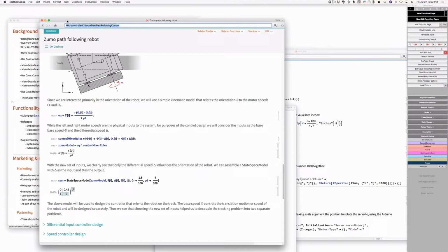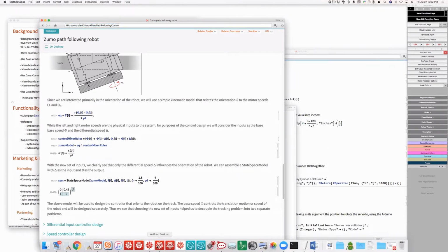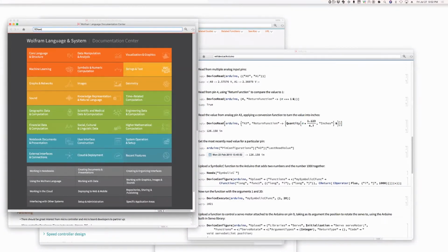So essentially what you're saying is the microcontroller is going to step through these difference equations based on the data it's receiving. So it needs to be discrete, it needs to be difference equations. Even if you model it using differential equations, you are responsible for discretizing it and making it difference equations. State space exists for both differential equations and difference equations. The one that the microcontroller ultimately wants is difference equations, because it needs to do things step by step. All right, let's look at the state space model.